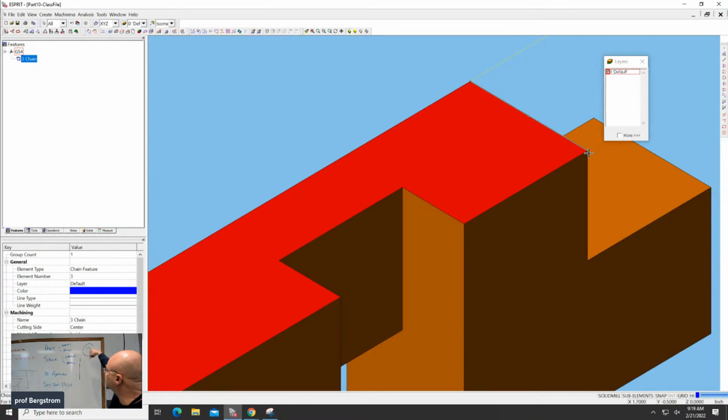And so the rotation of the tool will tend to make it roll along that surface that we want to make. And so this edge of the tool, as it rolls along that surface or as it climbs along that surface, is going to make that surface here. And then the bottom of the tool is going to make this surface down here, right? Okay.